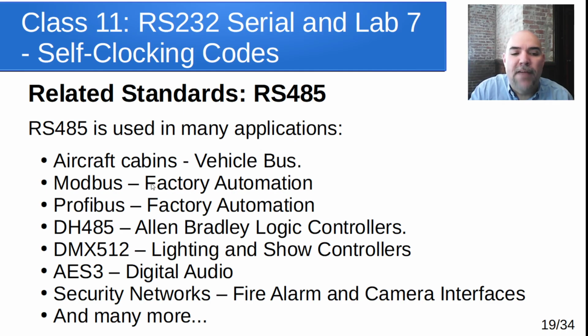But there's also factory and automation versions of that. There's a thing called Modbus, Profibus. Those are used for factory automation. Allen-Bradley makes a version of logic controllers that are used for, those of you who are in the CET degree might know what I'm talking about. But programmable logic controllers are essentially like a little computer inside of a device, and you program them using this thing called ladder logic. But the way they communicate with each other and with other devices is using this DH485, which is really just RS485 with a protocol sitting on top of it.